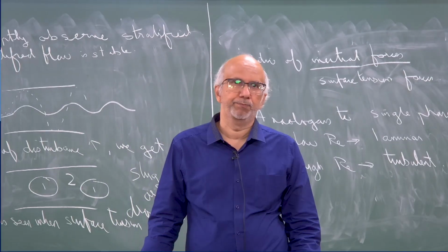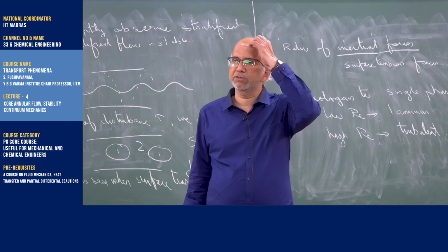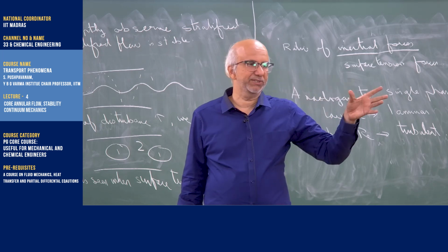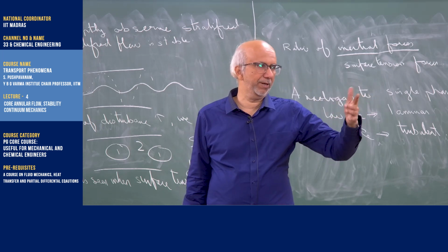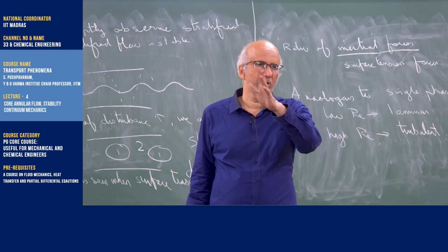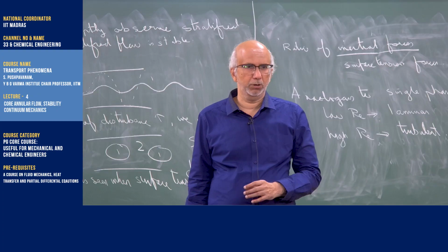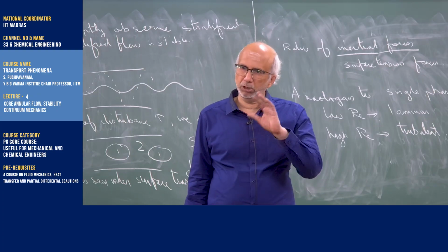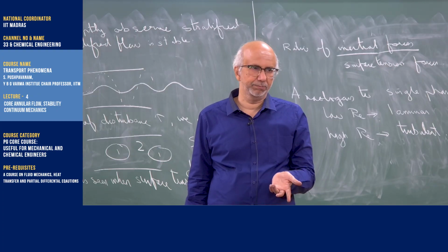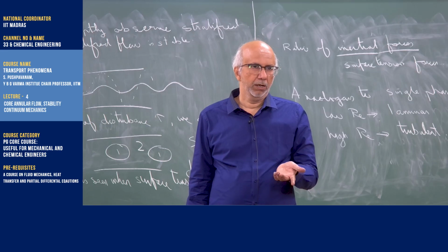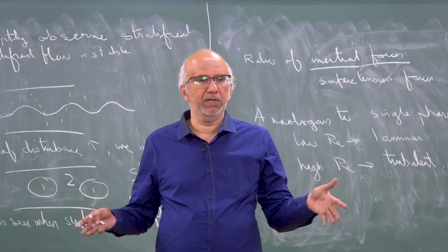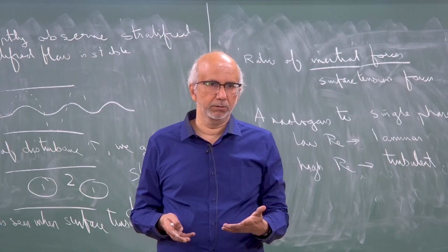See, the Hagen-Poiseuille velocity profile that you have, Vz of r equals dp by dz over mu times 1 minus r by R whole squared, which you found out for laminar flow, is going to be valid for all dp by dz, right. So you will say, look, I keep any dp by dz, I should get my parabolic profile.